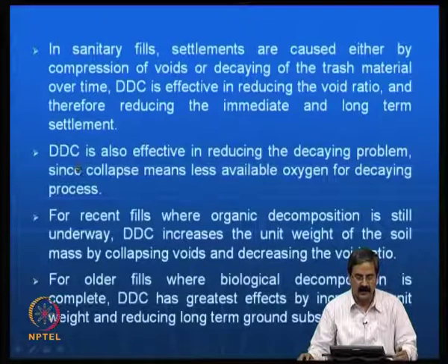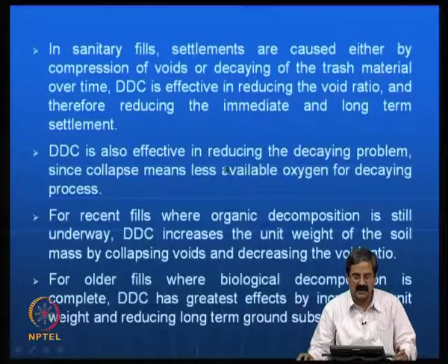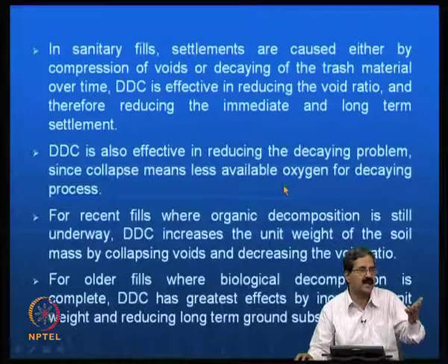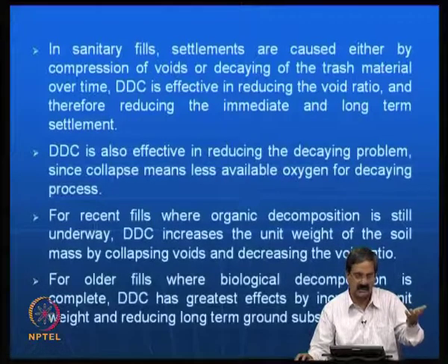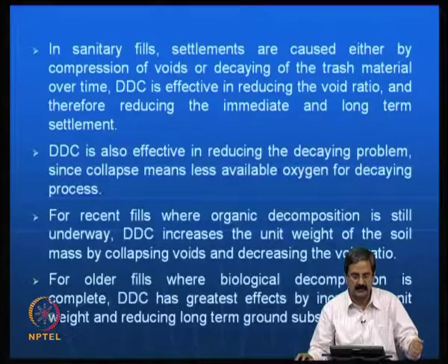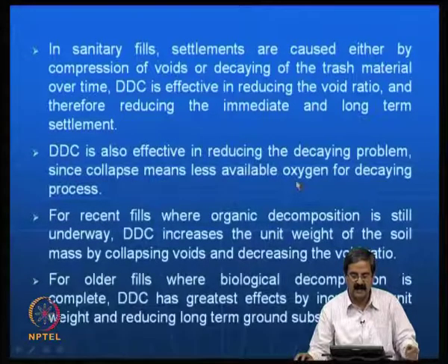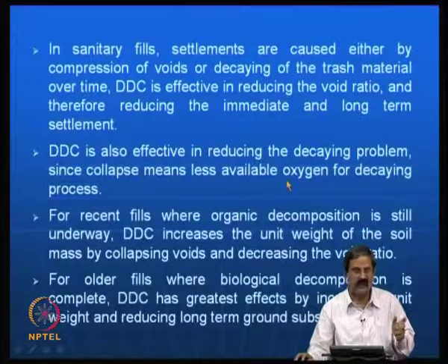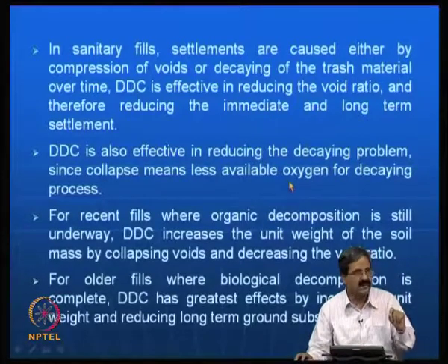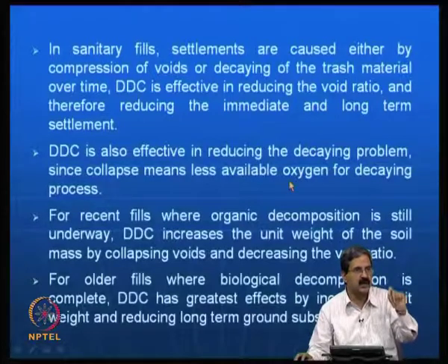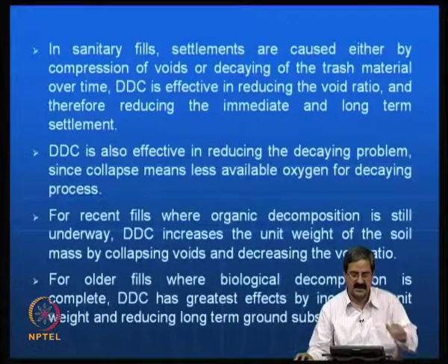A very important point is that dynamic compaction is also effective in reducing the decaying problem, because biodegradation activity occurs because of the availability of oxygen. So it is better that there is sometimes a collapse in the case of these materials, which makes the availability of oxygen less. Of course, only as long as the oxygen is available and the biodegradation is complete can you be very sure that the consolidation is complete.